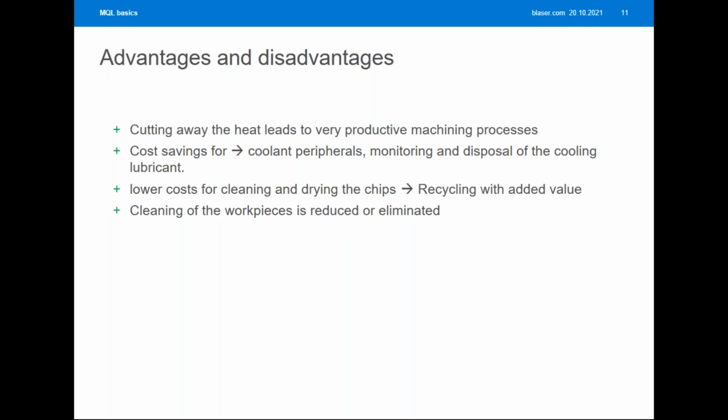There are lower costs for cleaning and drying the chips because you bring in less coolant. There is also less work to take this coolant off the workpieces. It also helps that the chips have a higher worth, a higher value for the customers, and sometimes cleaning of the workpieces is at least reduced or can be completely eliminated. This depends a lot on what industry we are talking about. So just saying the cleaning of workpieces is eliminated is not always possible.